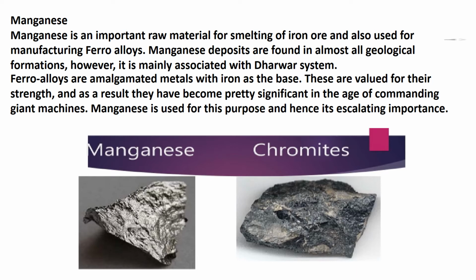Amalgamation is a process of extracting metals such as native gold and silver from their ores by the addition of small quantities of mercury to the stamping or grinding unit, so that the resulting amalgam is caught on mercury-coated copper plates, from which it is then scraped. The precious metal is then recovered by distilling the mercury.